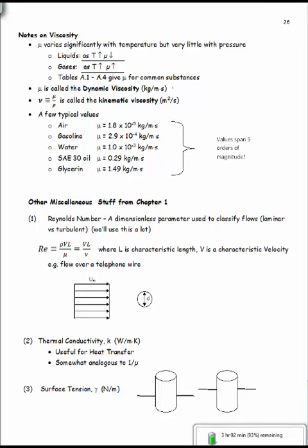Mu, we've been calling this viscosity. It's really dynamic viscosity. Okay, and we differentiate that from what we call the kinematic viscosity. In kinematic viscosity, Greek nu, okay, it looks kind of like a V. That's defined as mu over rho, and really it's just a shortcut so that we don't have to look up both mu and rho and then divide. Instead, we just look up nu sometimes.